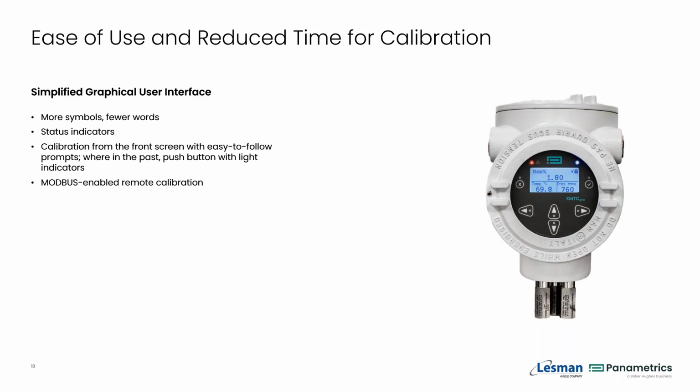The XMTCpro replaces the XMTC in our product line, which replaced the TMO2TC before it. The TMO2TC was an analog transmitter where you actually had to use potentiometers to set the 4 milliamp and the 20 milliamp. We are still getting phone calls for service on those transmitters, and those have been working now for 25 to 30 years.